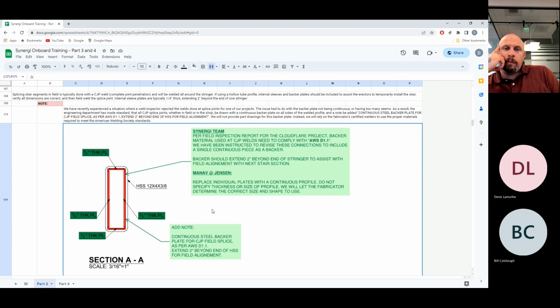There were, I believe, eight holes on each side of the splice that we would fit the plate into position, remove the bolt, fill that weld for each side, and then ship that off to where the field could reassemble that in its exact position using the bolts again, and one by one fill those and then do their penetration weld.